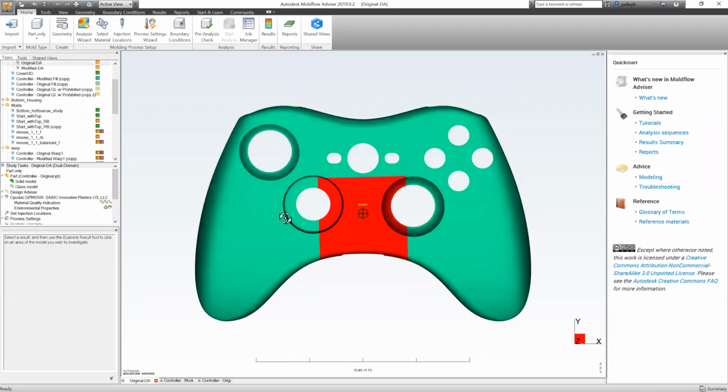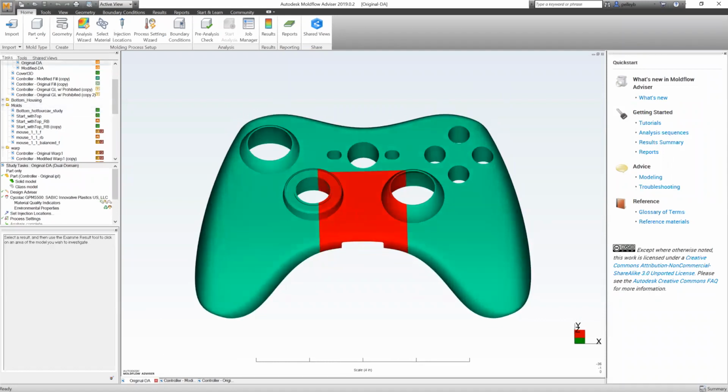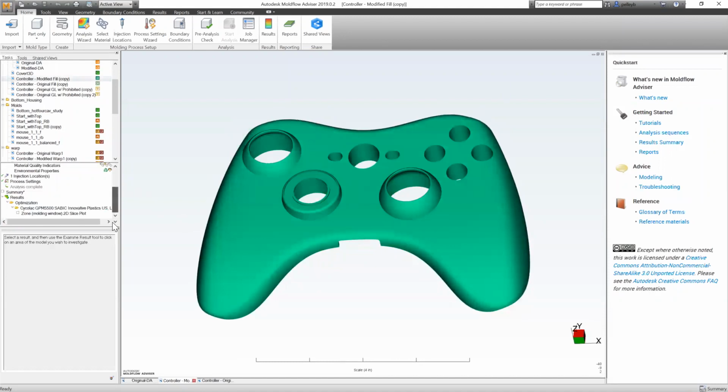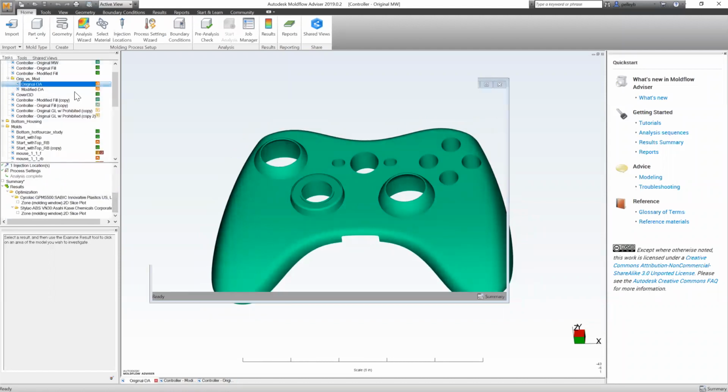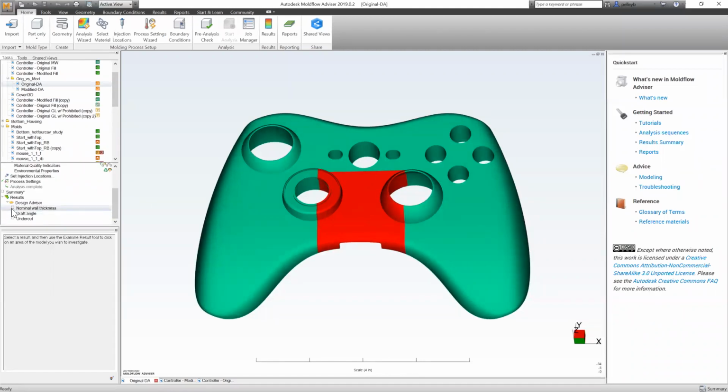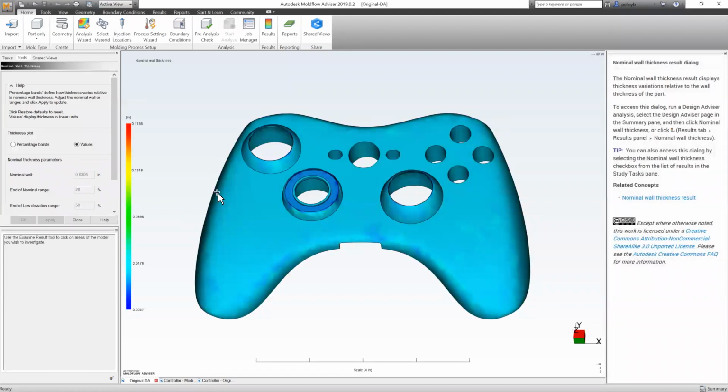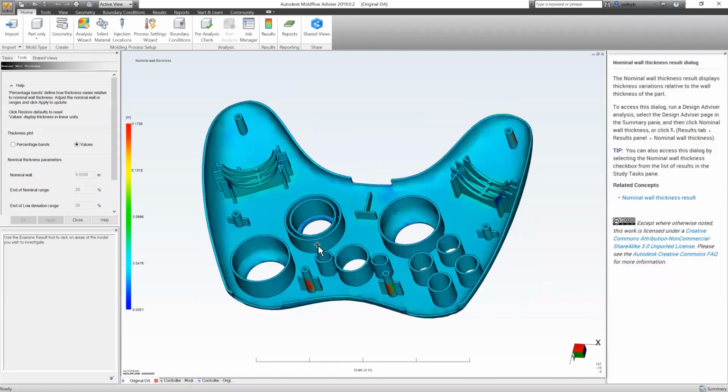Those are the three key variables that really make up a lot of the issues we see downstream as far as manufacturability. If you look at the geometry itself, we've got some things that we can discuss. By far, wall thickness variation is the one diagnostic, if you only had one, that you would go to, because it tells you so much about how the mold or cavity will be filled, where you're going to see different thermal loads as far as thick versus thin areas, flow resistance, areas that are going to hold up the cycle, economics. And this is all simply done with one result.